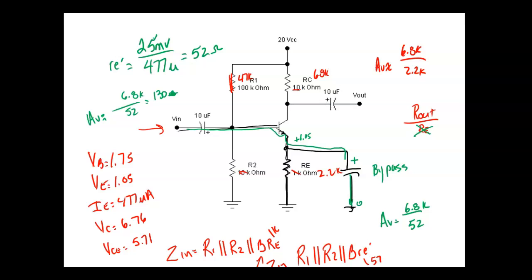So like I said, if you see on test 3 a question that says IC equals IB, you're going to say IE equals IC, that's going to be false, right? You understand? If it says approximately, then it's going to be true. So no, we don't know beta. Well, like I said, for this transistor, beta is roughly 100 for this circuit. And once beta is set, it's not going to change with temperature anymore. Why is it not going to change with temperature anymore?